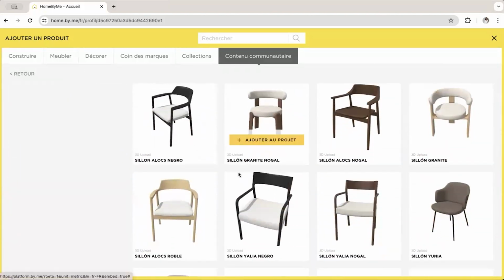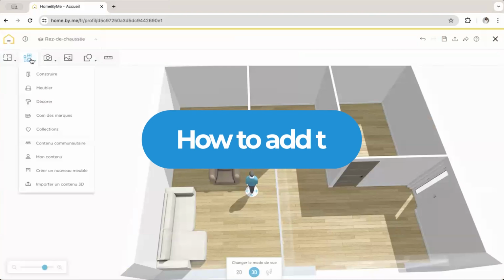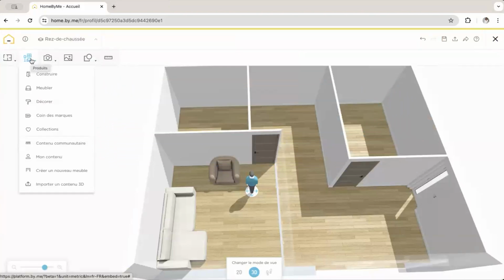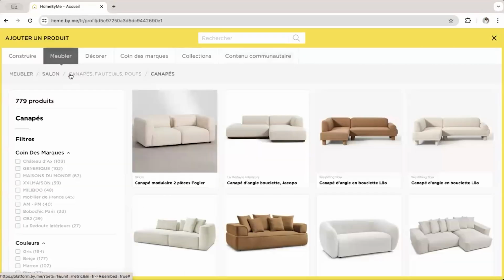So, that's great. Now you need to add textures, and that's where you have a new tool that's really great. Want to add textures? So wallpaper, yes, wallpaper in wall coverings, whatever you want. You're going to go to the company library and the search bar. At the very top, you're going to do a freeform search.